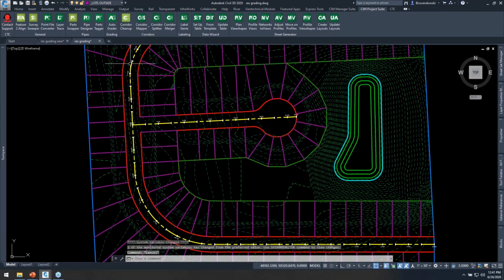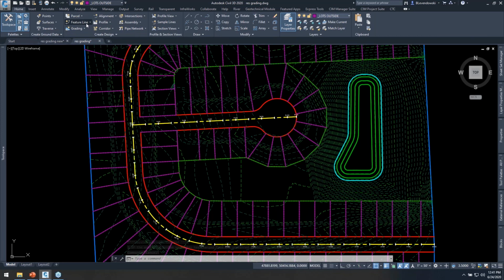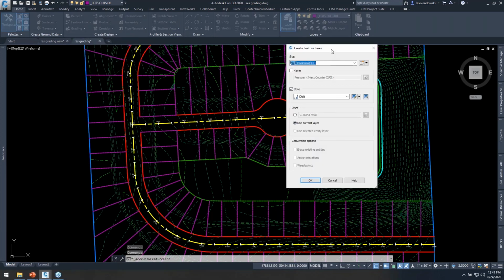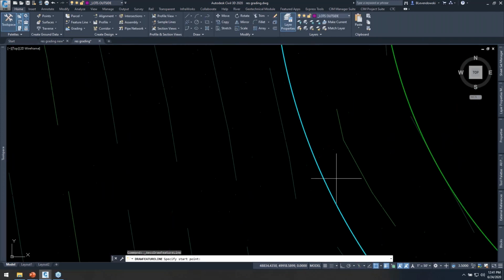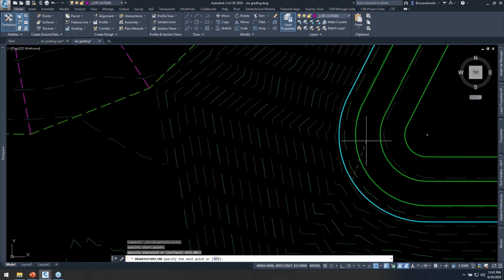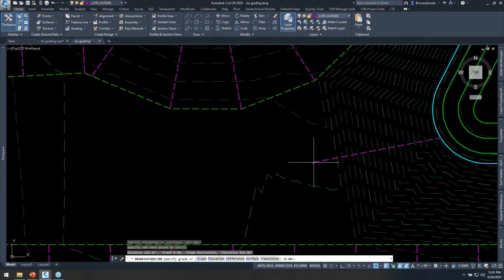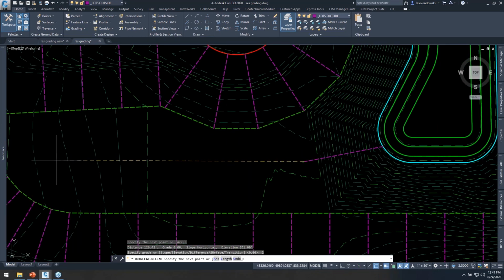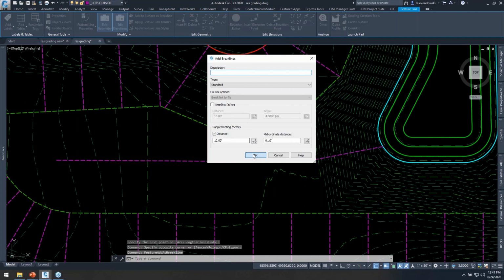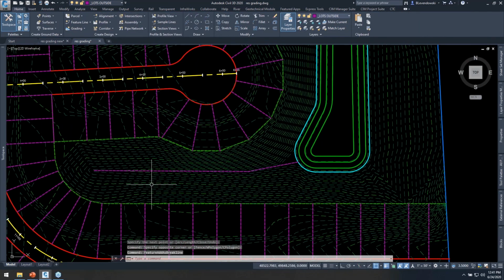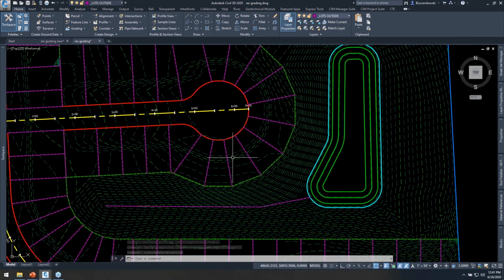Now other miscellaneous stuff where it's really kind of a unique independent decision, or like dropping a swale in here, you can just continue to do that as you normally would. Coming in here, I'm going to snap to this, right? We just create a feature line up at a 2%, okay? And then you just add this in like you normally would, and we can control that, putting in swales, berms, however you might want.